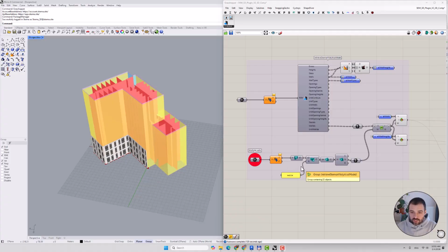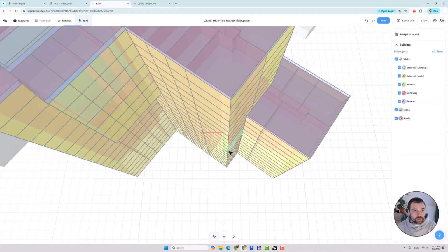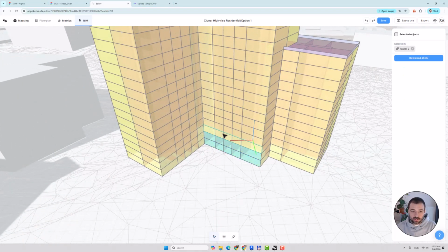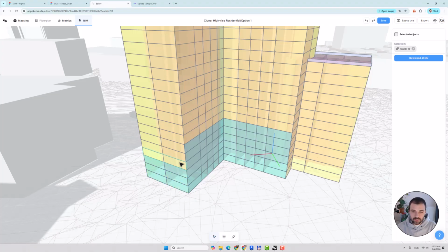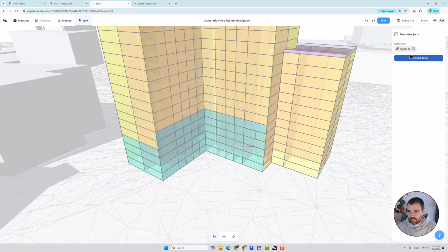Another important step is specifying which elements from the analytical model the script should use. We can do it by going back to Schema, going to the Beam tab, and selecting a set of walls. In my case, I need to select the walls in pairs, and I can select walls on the opposite sides just to validate the grouping logic. So I can see that I have 16 walls selected.